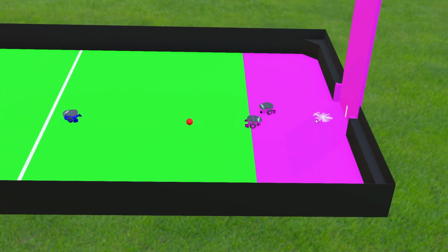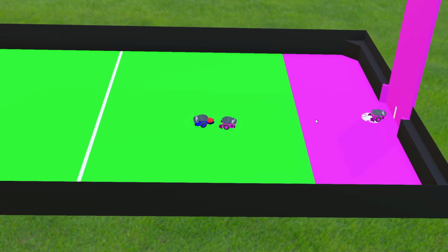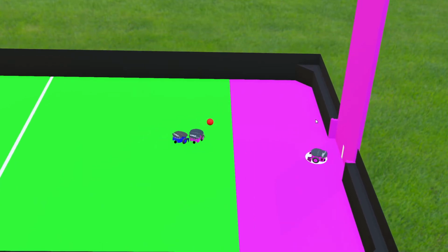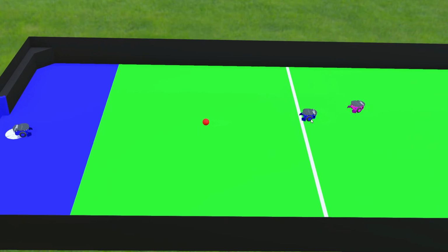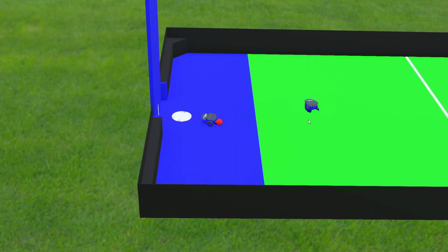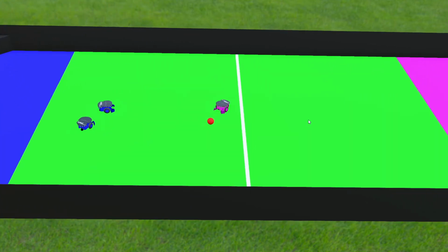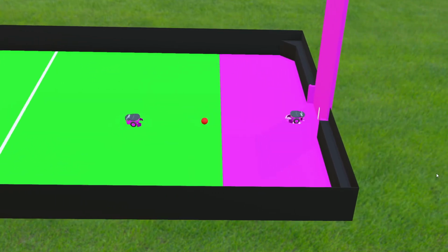The other thing about the defender is it's actually got quite a number of distance sensors that are pointing forward, and they're all very closely aligned to each other. They kind of spray out in front of it. The idea there is that it's not just relying on one single beam to trigger its defensive mode, that the ball would trigger at least one of those distance sensors in front of it. So there's no way that the defender won't chase the ball when it's within range.